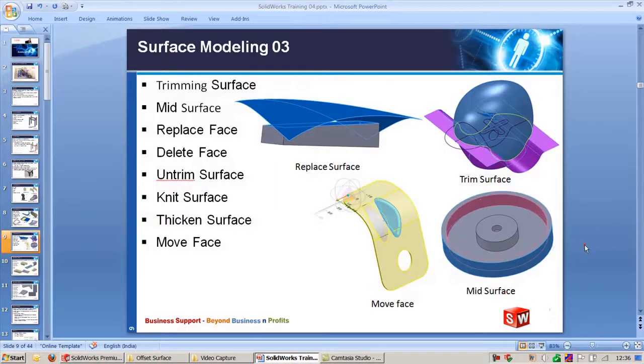And that's all about surface modeling in SolidWorks. Using these surface modeling tools, definitely you will be able to design any type of model with respect to class A or class B. Anyhow, we have advanced modeling tools like flex, freeform, deform, which are once again helpful in modifying both solid and surface models, not sheet metal. Using these advanced commands, you can do any consumer product. Using flex, you can do a twist or bend for both solid and surface modeling. That's all about doing surface modeling in SolidWorks.